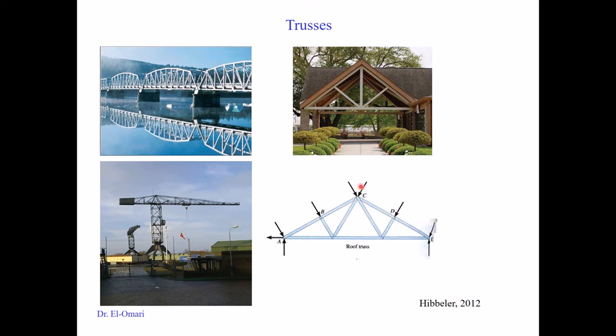The main assumptions are that the external loads or forces are always acting at the pins, trying to avoid the loads acting in between the pins, so as to avoid having bending or bending moment. Another assumption is that the weight of the members is neglected, because the weight as compared to the external loads is very low to be neglected.